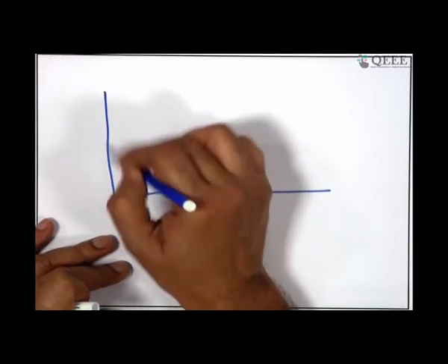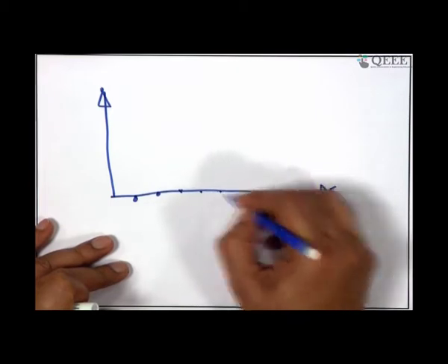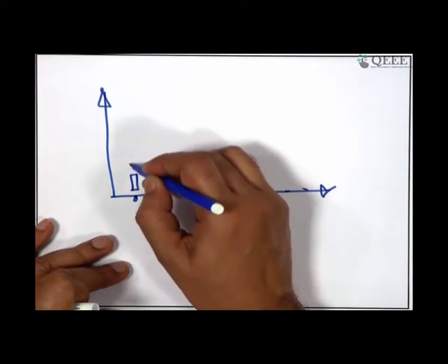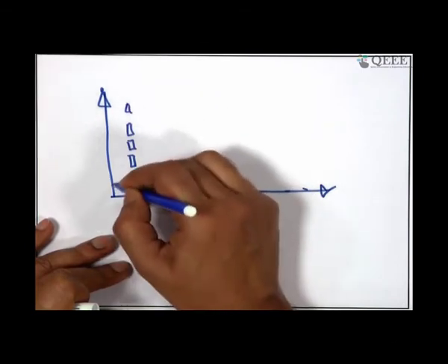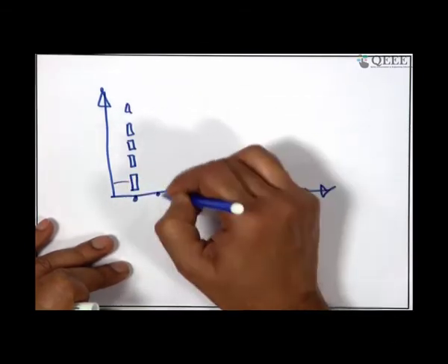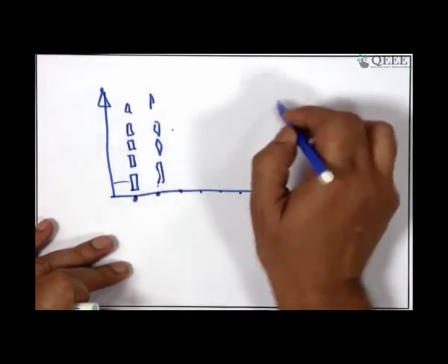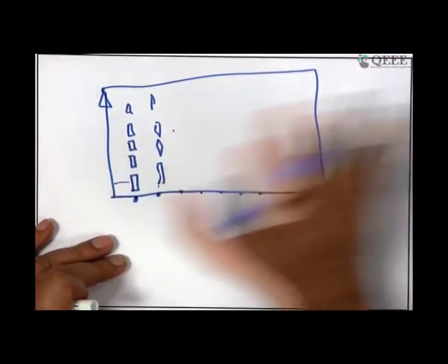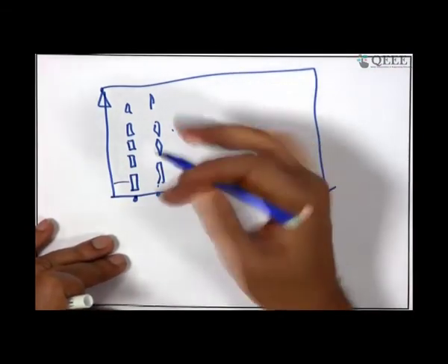The other way, what we could have done, instead of the influence line, is think of different sections on the beam, and at each section indicate the values of the bending moment with a bar chart or some values as the unit load moves. So, as the unit load moves, this is the value here, as the unit load moves, this is the value here, and reading that bar chart type of thing, I could have devised some methodologies conveniently replacing the influence line. I am telling you that is not going to happen. The influence line is absolutely fine with the engineers. I am telling you what is the alternative.